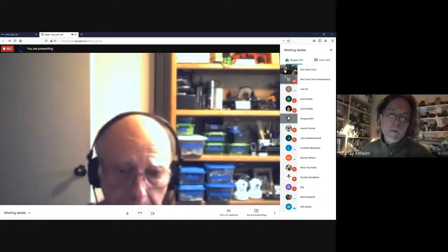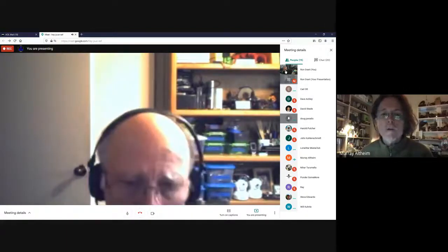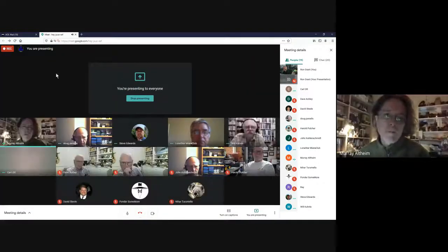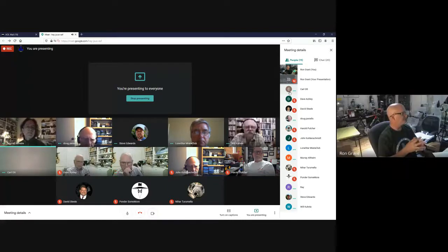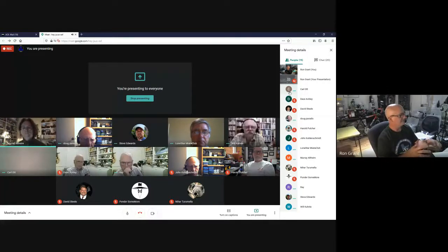So if you were to use a camera, what you could do is choose a specific array of pixels off the camera and ignore the rest of the camera information and just grab, let's say, 16 or 32 or 64 pixels in an array off the camera and sample those. Exactly, as if you were doing it within a linear array. Yes, that's been the approach I've taken. So that's kind of what motivated this simulator a little bit, except I simplified it in that I am using a look-down view instead of a camera-type view that's subject to perspective and all that.